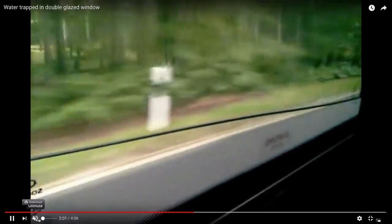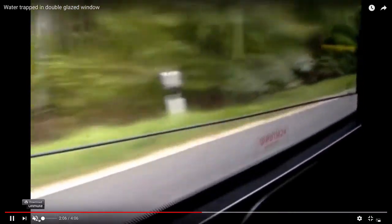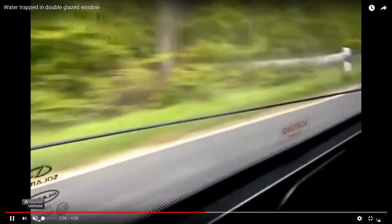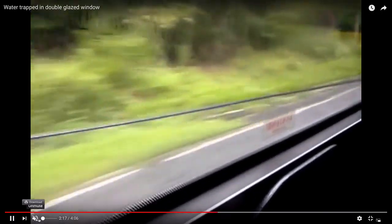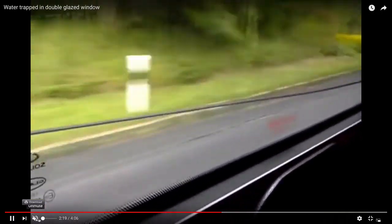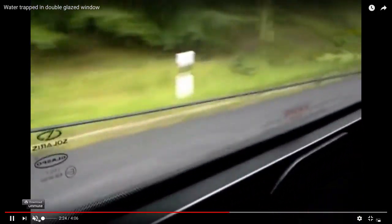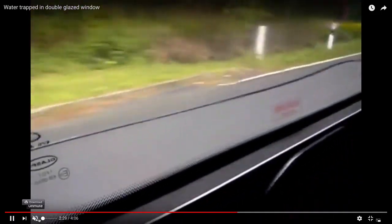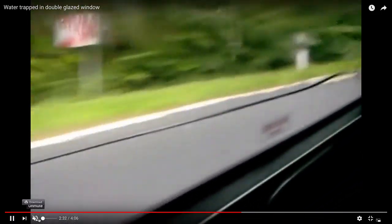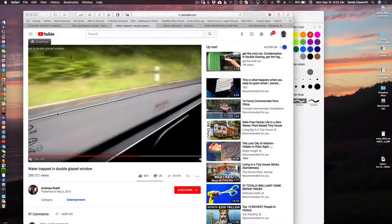We made the point that when you look at the tank cars that you see that pull oil across the country, the Bakken oil, they're not just flat on the top, but they have an inclination at both ends and a depressed filling manhole in the middle. And that is so that when these things decelerate, it doesn't pile up at the end and pop the hatch and have a spill. And I presume that's exactly the design reason for that. And this is really the mechanism that's going on. So today we'll spend some time talking about accelerating fluids in static fluids.